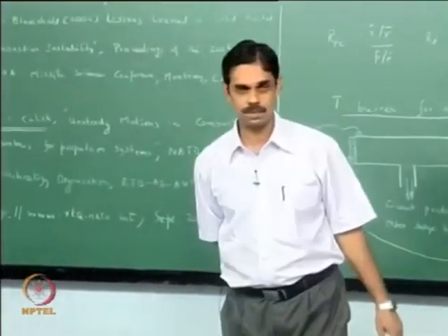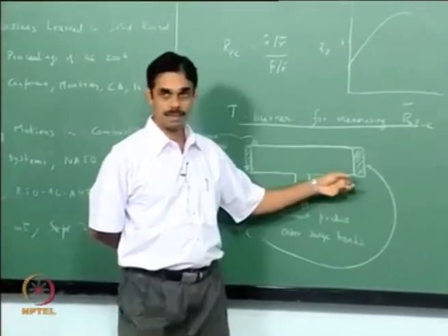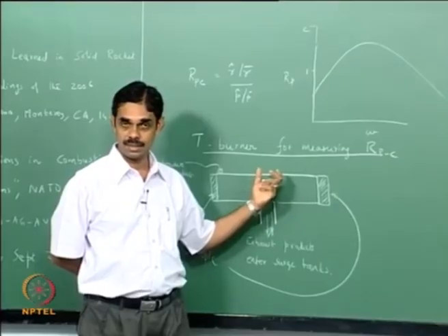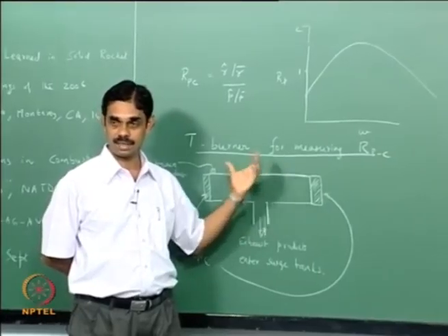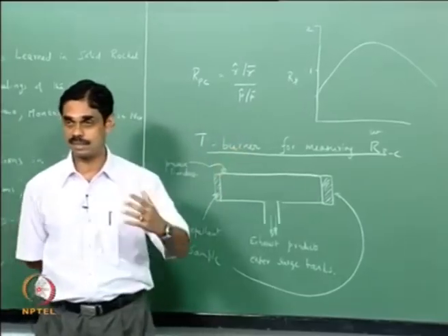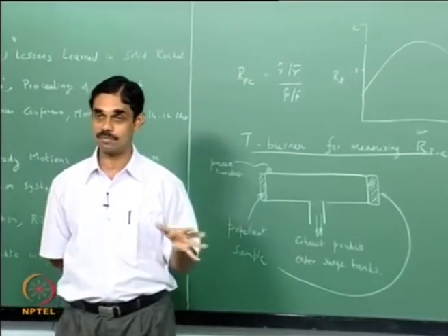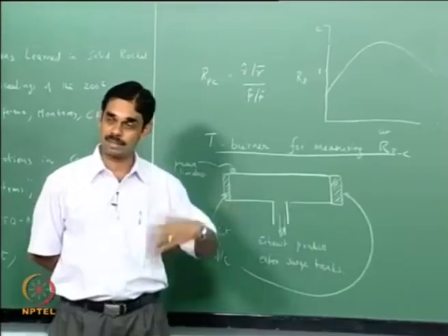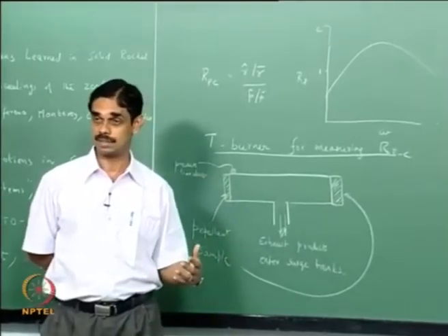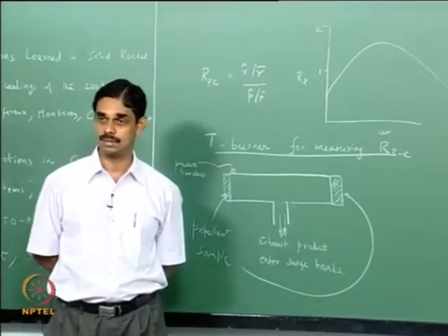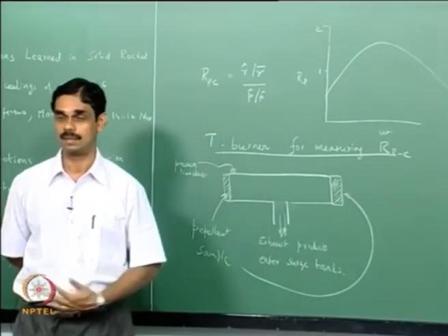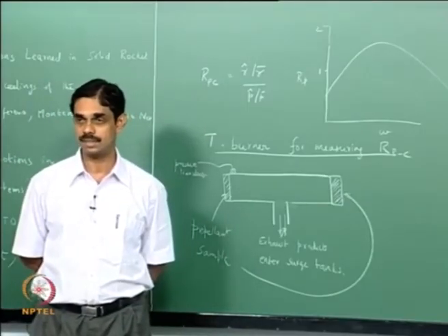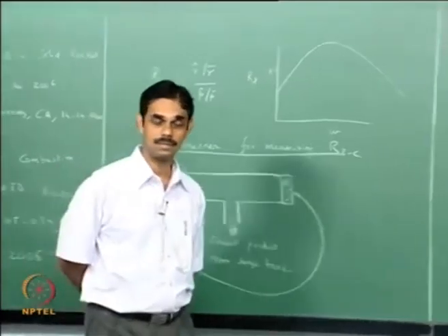You are talking about a very important point, because once the burning gets completed, the temperature might change, so your natural frequency will change. But you will have to do this at various lengths and then determine alpha 1 minus alpha 2 at various lengths, and for various frequencies, and the alpha 2 corresponding to this experiment may have to be determined from some other experiments because the temperature changes. So there has to be some correction to it. Strictly speaking, it may not vary so much with temperature, but yes, this is an important point. Any other question?